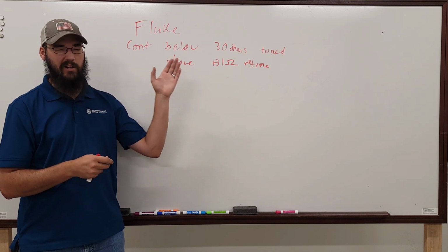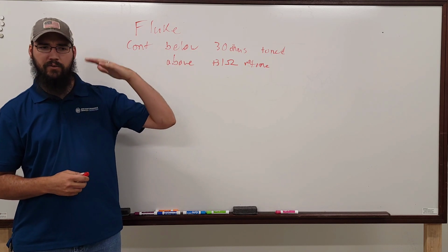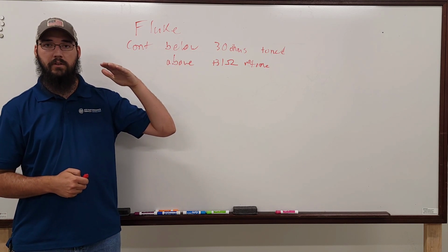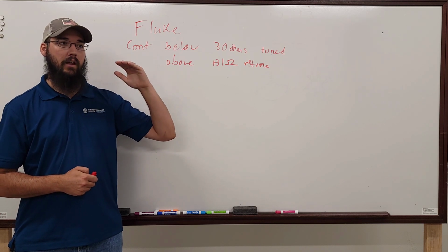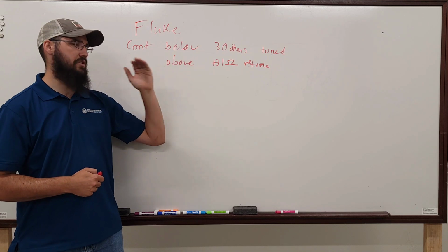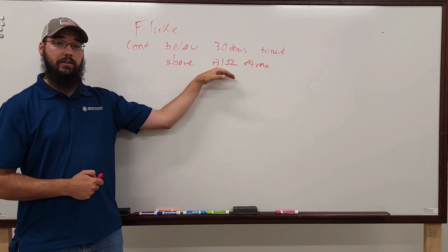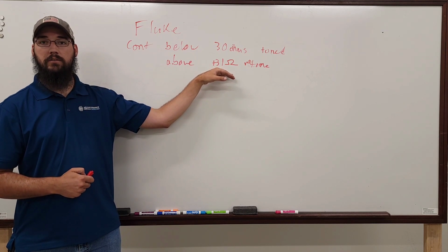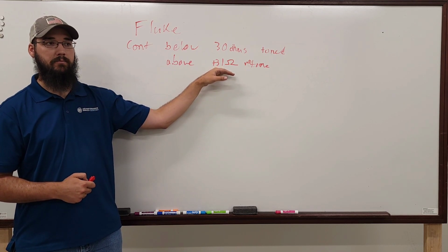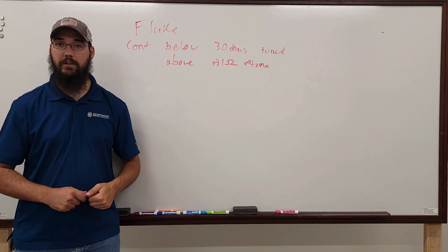Many meters, which I think Fieldpiece, that cutoff is like 10 or 15 ohms. Anything more than that, it's not going to give you a tone. I think Fluke is actually somewhere between 30 and 50, legitimately. That's all it takes, that 1 ohm above. Does it change the outcome? No. You get the same exact result, you just don't know that you did.